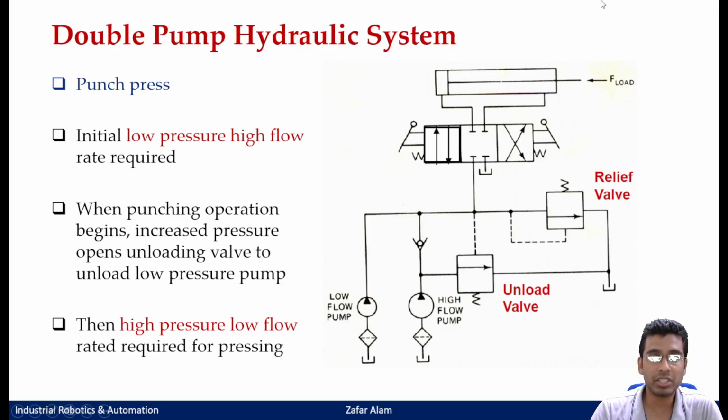When your pressure starts to build, it would build in this line. Now this valve limit is set at, say, 20 bar pressure. At 20 bar, when this entire line is at 20 bar pressure, the pressure cannot go backward here since this is a check valve.